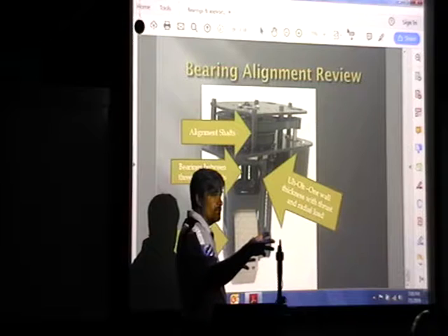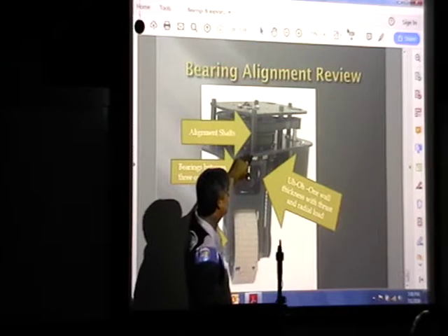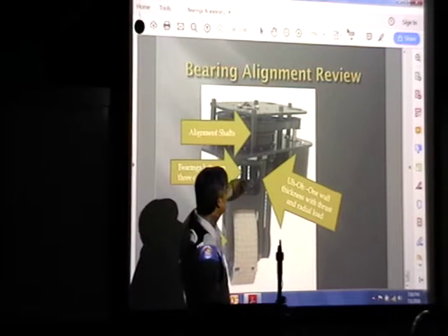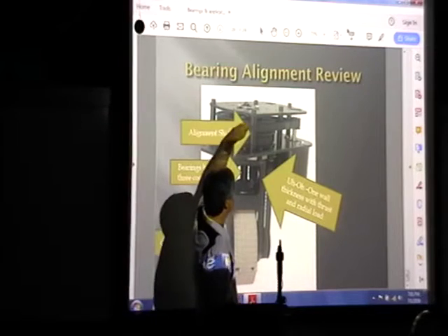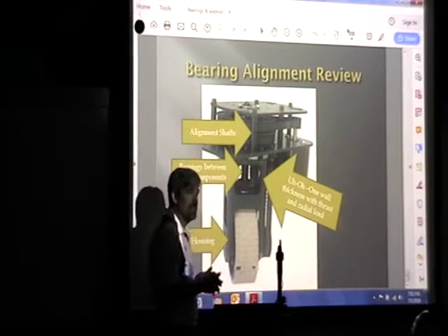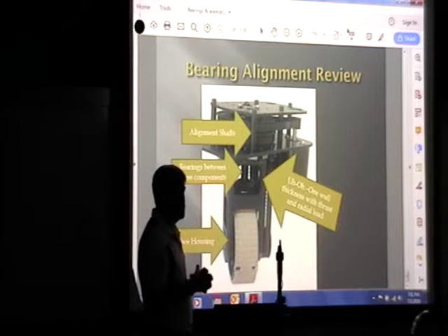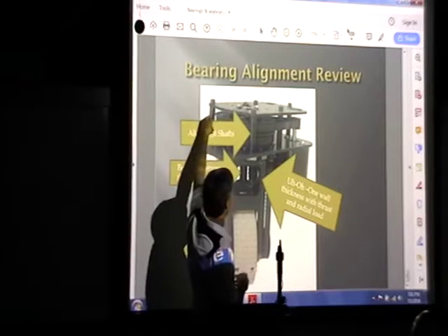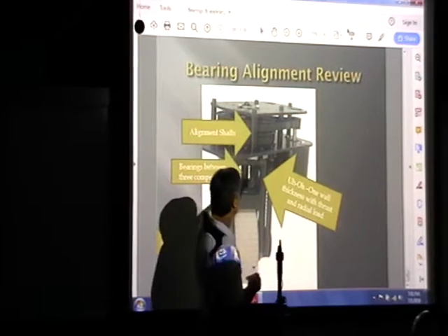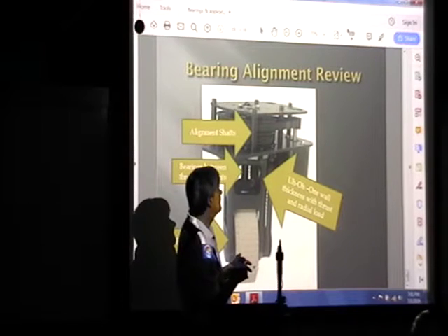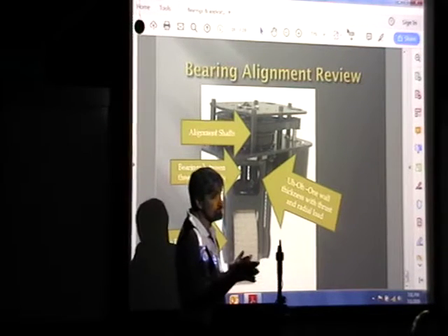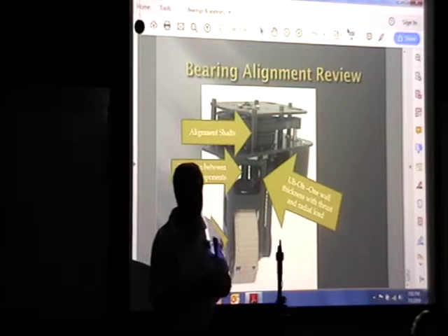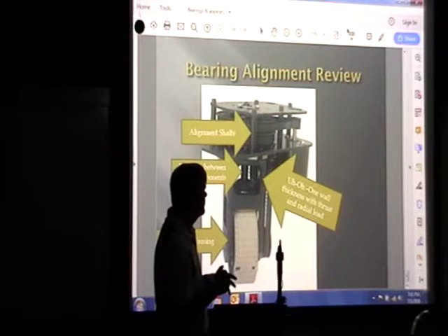It usually doesn't work. And certainly not in a situation where you've got these risers in between this bearing mount and this bearing mount. Because anytime that you put 1, 2, and 3 structures together, there's going to be some misalignment between those structures. This is attempting, I believe, to use these shafts as some sort of alignment to keep this bearing and this bearing somewhat straight on. But at the same time, if there's a third bearing in here, I don't think that'll work. Not very well anyway, unless you're sending those parts out for machining as well.